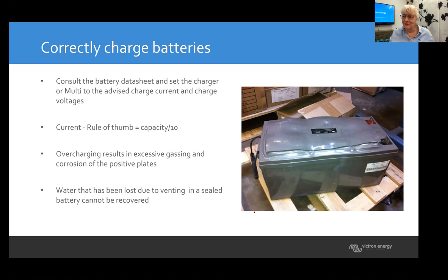charge happening, all the energy is being used to split the water up into 2 components. You create a lot of gas. So overcharging, or battery damage and then trying to charge it, will result in gassing and corrosion of the plates. But the gas can't go away, and there's an emergency vent that will let the gas out. Sometimes you create so much that the whole battery starts bulging. That's all not a good sign. Quite often not warranty, although people get really shocked when they see this.